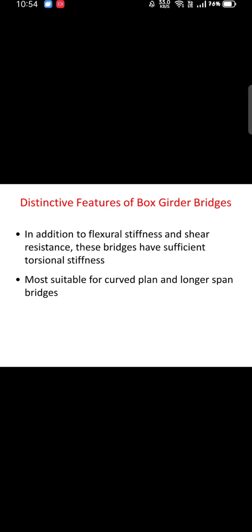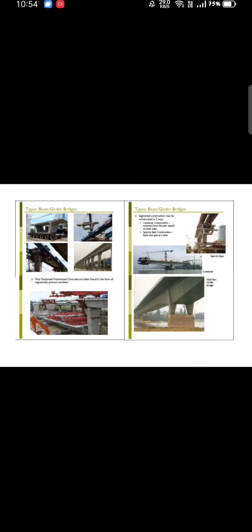So these are distinctive features of box girder bridges. In addition to the flexural stiffness and shear resistance, these bridges have sufficient torsional stiffness as well. These are more suitable for curved plan and longer span bridges. So you can see the pictures here.